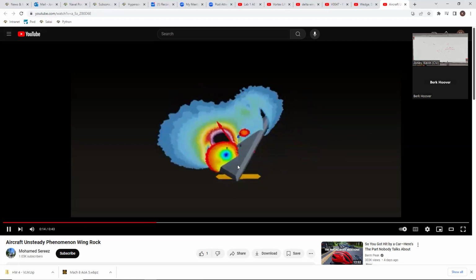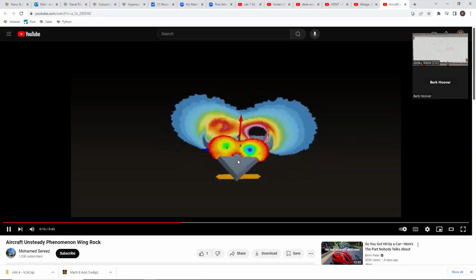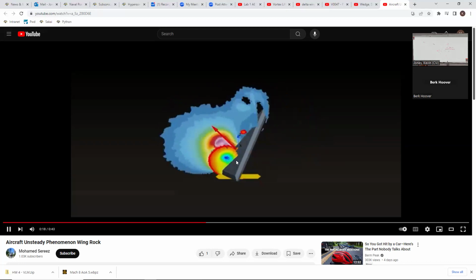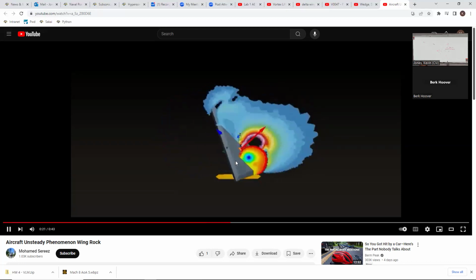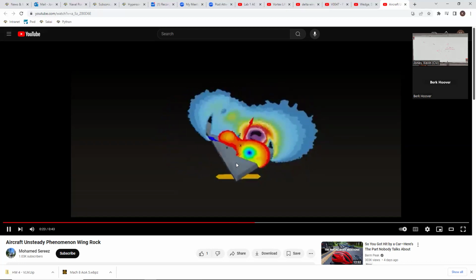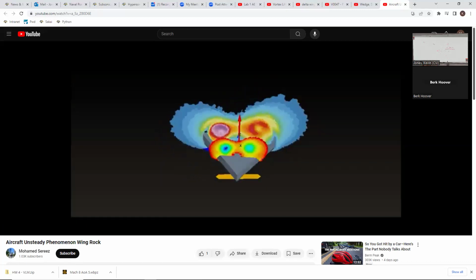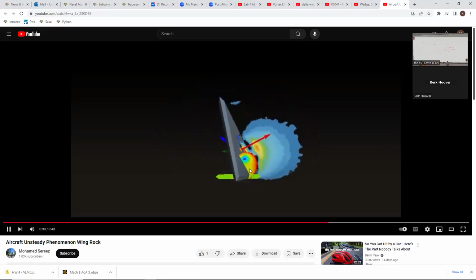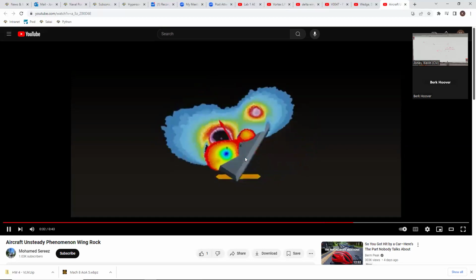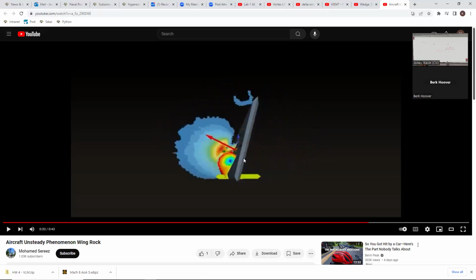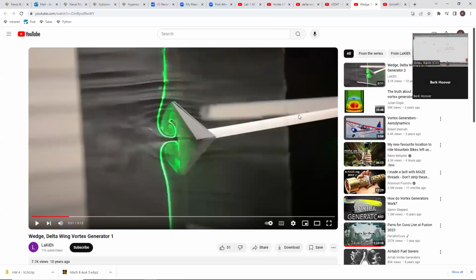So they'll actually get into this natural mode, and real aircraft will do that. Some of the early flight tests I saw with F-16, they actually ran into such high alpha that the airplane would naturally go into this. Model aircraft do this all the time, delta wings, without some kind of stabilization scheme in there. Usually it's not divergent. It'll hit a certain angle or a certain roll angle, and then it'll self-correct. Anyway, kind of a natural phenomenon.